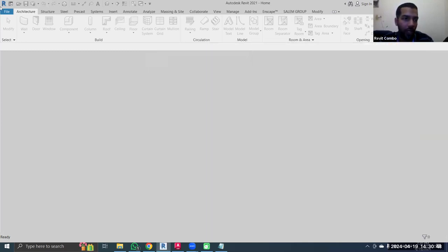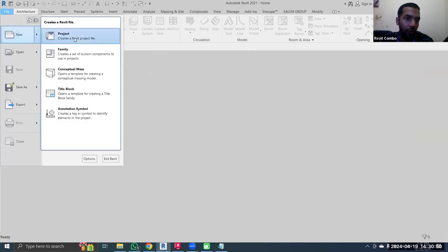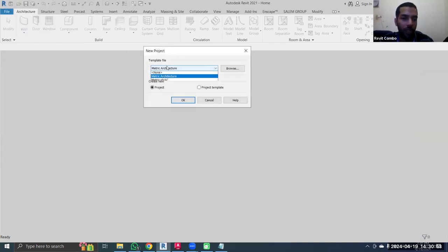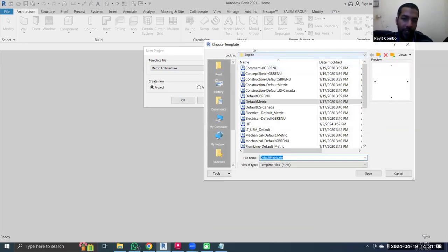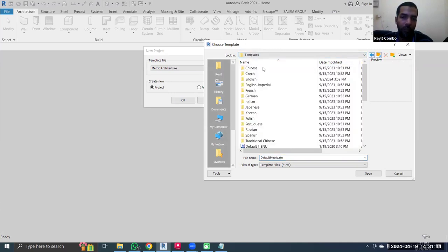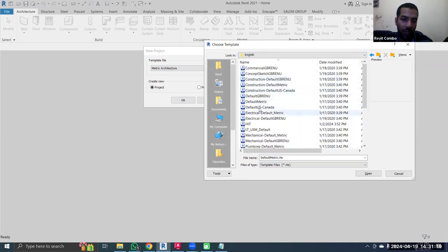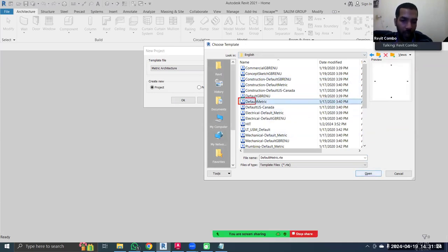So how do you do that? Go to the File menu and say New Project. When you take a new project, you may notice there may be some list here. If there is no list here, don't worry. Just go to Browse. When you go to Browse, make sure you are looking in the folder of English. English is millimeters, or we call it US metric. Some versions may have a US metric. So you can select the US metric here, which is going to be English, and then select the default metric. Remember, the default metric is the one for architecture.